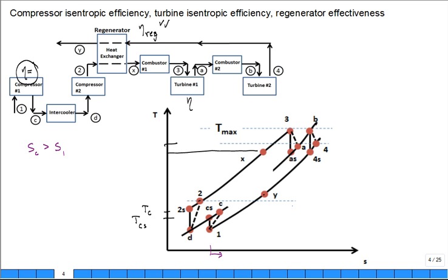We've analyzed compressors before. So you have to analyze that component. And for this problem, you might have to analyze it twice because you have two compressors. So the same thing, from D to 2s and then D to 2. Now, if you come to the turbine, you have a higher temperature. TA is higher than TAs. You get less work out of the turbine because of the irreversibilities. Yet you're still on the same pressure. That's all the same pressure line.